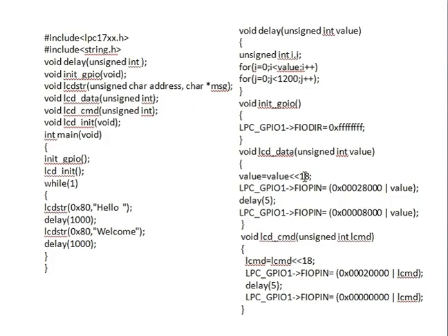So the value is shifted, then we perform this OR operation. So we take a data 0x302000, this should be ORed with LCD command. So LCD command, we know it is 38 data shifted with 18 bits. So from 18 to 25 you have a data, and other remaining bits will be set to 0. That complete 32 bit data is ORed with a data